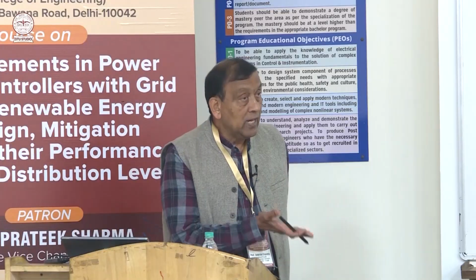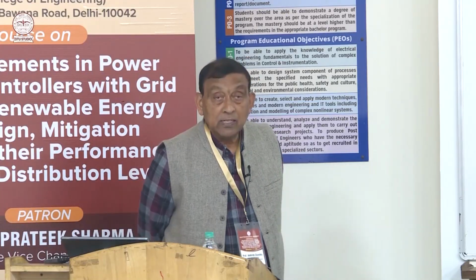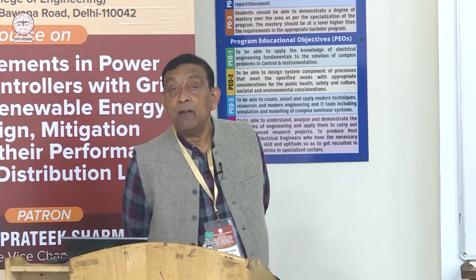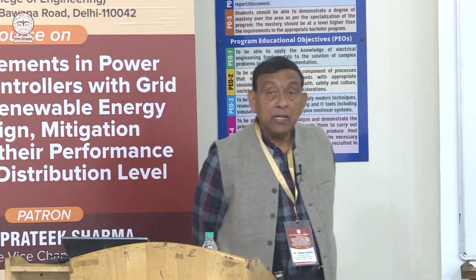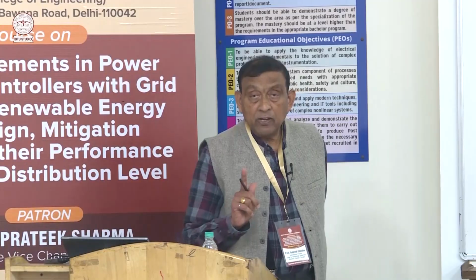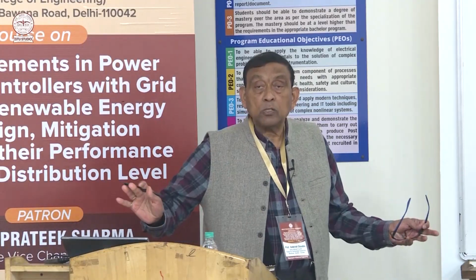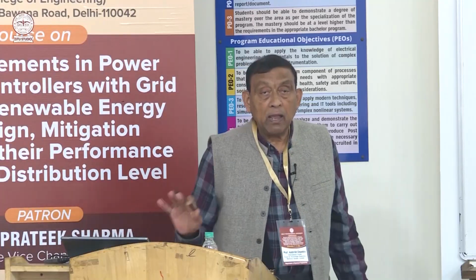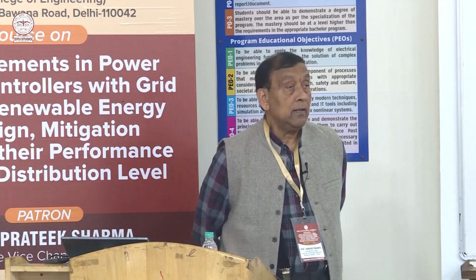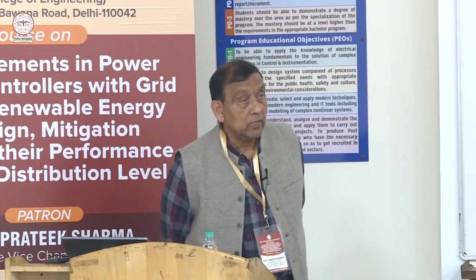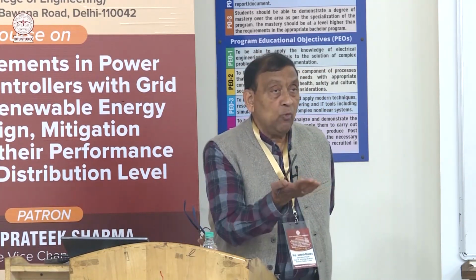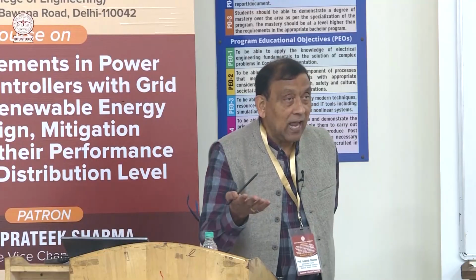Although a single 3-phase transformer has higher efficiency than 3 single-phase transformers. 1 3-phase transformer is a big box, but 3 single-phase transformers are small boxes, and their efficiency is a little bit lower than 1 3-phase transformer. And then what if you want an emergency transformer?